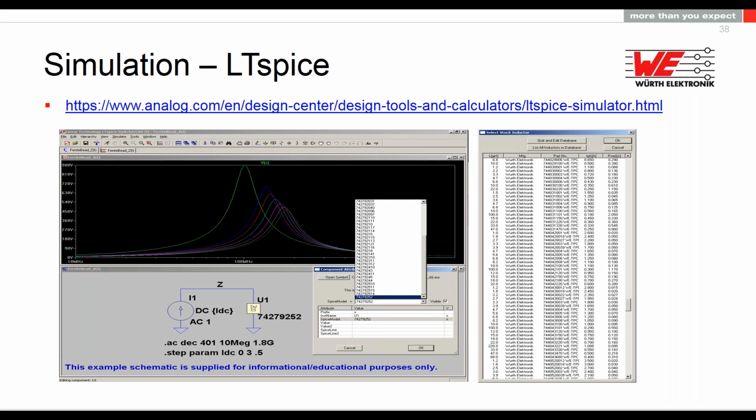I'm really amazed about Mike Engelhardt, how funny it is. Free of charge software can do so many interesting things, like even simulating conducted emission. So it's really crazy when you measure and you see it's almost the same. It is exactly like expected. And if you have a good model of the components, of course it will give you the real values.